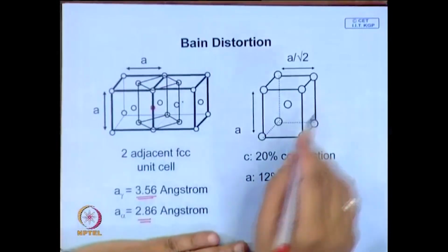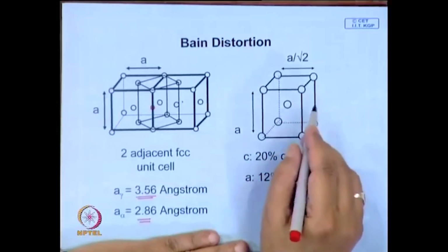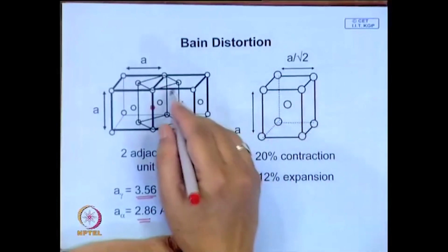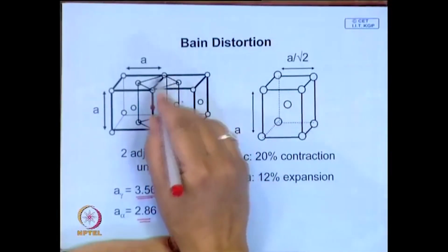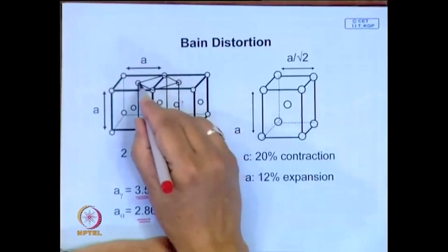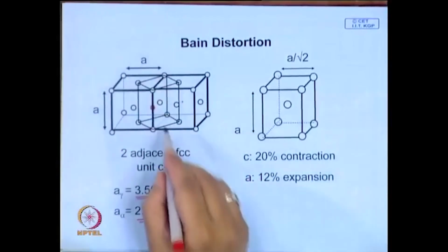And look at it: at very low carbon concentration, martensite can be almost considered as a BCC, and look at how a BCC structure can form over here. So, look at this cell which is drawn here, this particular cell.